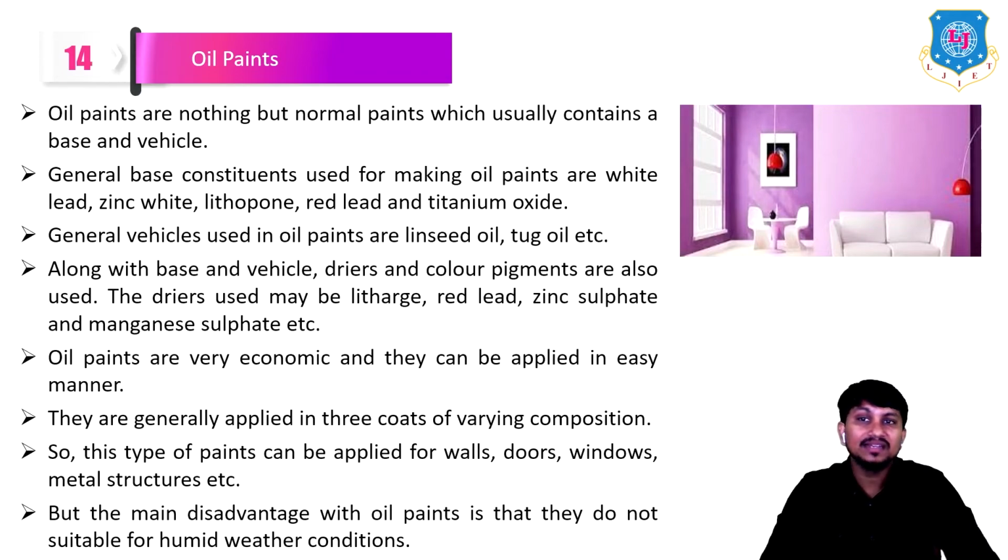But the main disadvantage of oil paint is that it is not suitable for humid weather conditions, because it gets some defects after some years. So if there is a humid weather condition, you should avoid this type of oil paint.